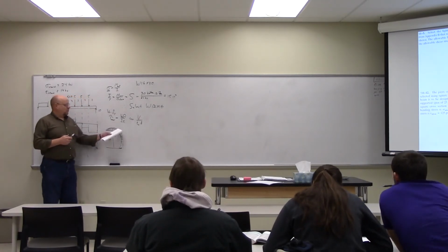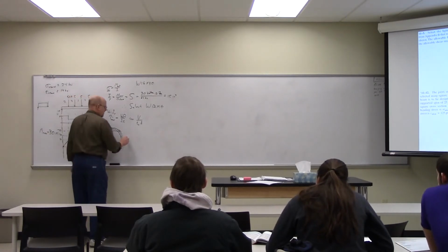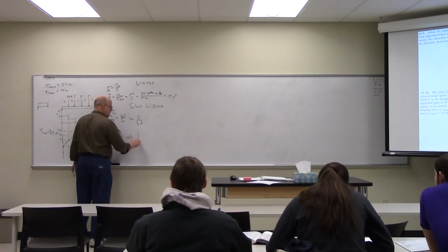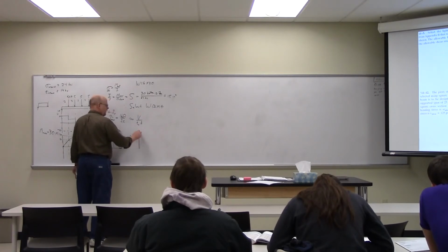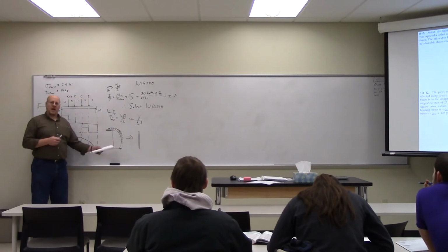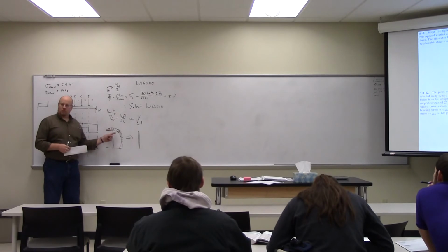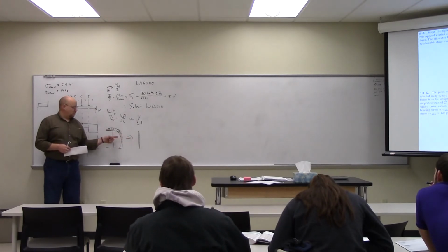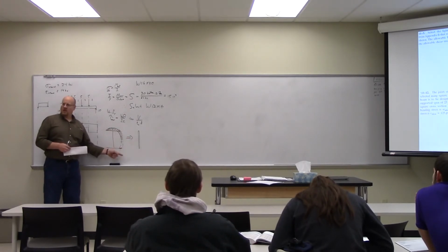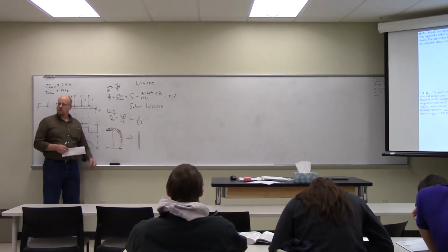Because so little shear load is borne in the flange, they're essentially saying, well, let's just replace this with a single web that runs the full height, and find what the average shear stress is in that. Because there's just this parabolic distribution here. If I find the average shear stress, by and large, it's going to be at or above the value of the peak shear stress.